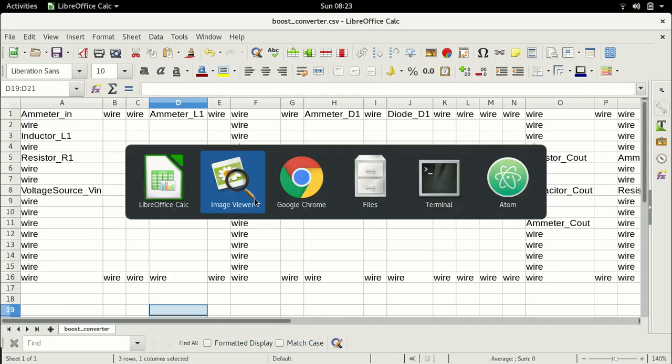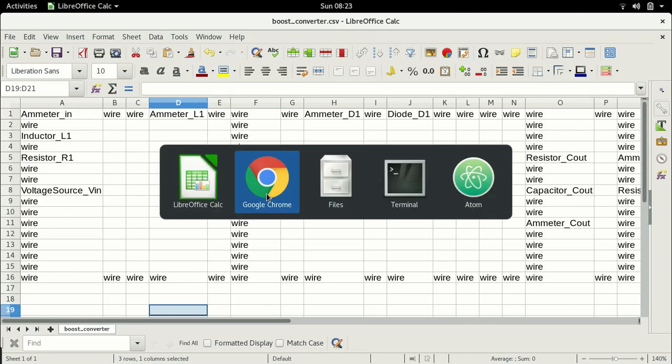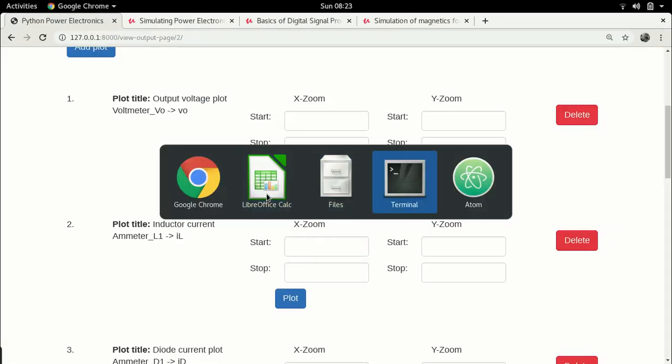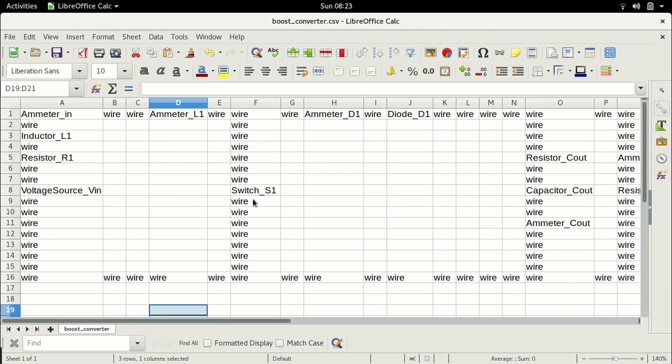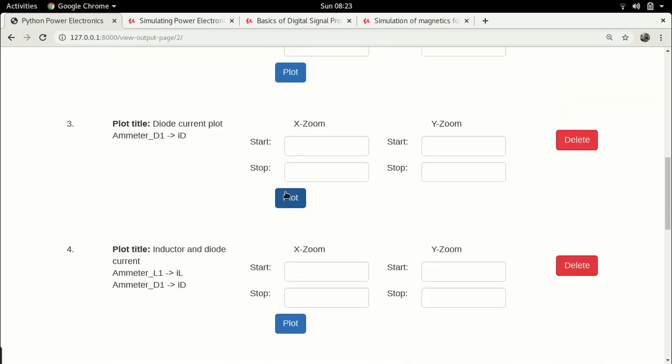Now, let's look at something else at the same time. We can measure the voltage and the current across the switch as well. This will tell you about the stresses in the switch. But what is important to understand through this simulation, let me see what else we can plot. The others you don't really need to look at because they would also be similar. For example, if you plot the diode current, that would also be at the same level because the same current is also flowing through the diode because the diode has to freewheel.